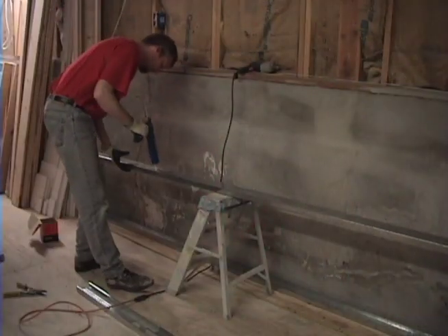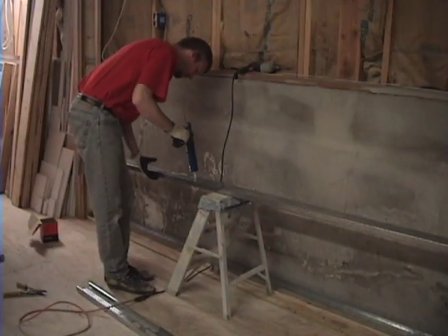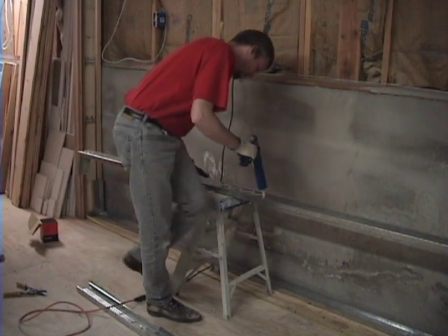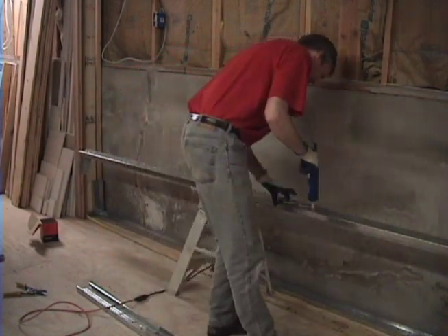Then place a bead of construction glue on the top plate to hold it in place. This is one advantage of steel over wood, is that they can be glued in place and run the screws in later. Well, now you're ready to put the studs in. Just like with wood, it's important to measure each one individually, but the advantage of steel is that it doesn't need to be as exact. It can actually be within a 1/4 inch of exact and still work out just fine.